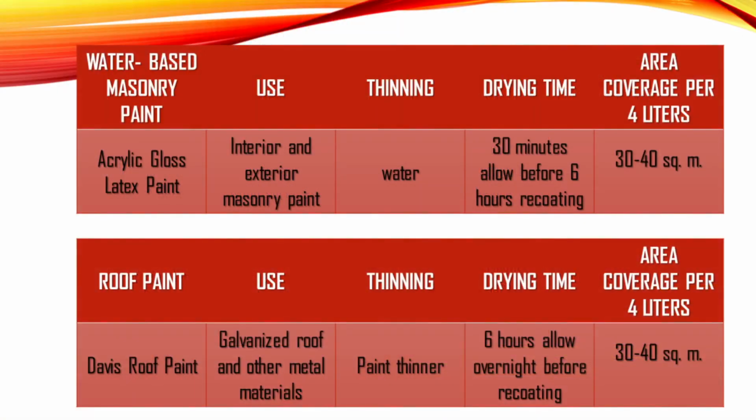An example of water-based masonry paint is acrylic gloss latex paint. It is used for interior and exterior masonry, with water as thinning, a drying time of 30 minutes allowable before recoating up to 6 hours, and 30 to 40 square meters of area coverage per 4 liters.